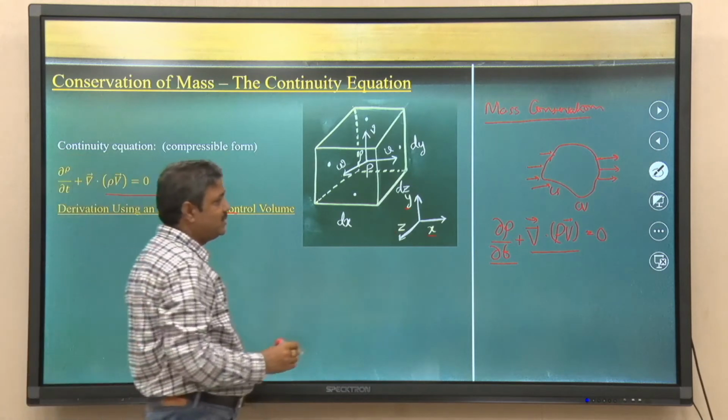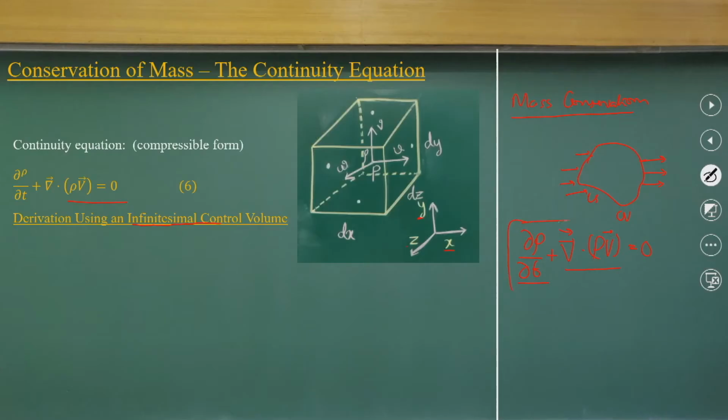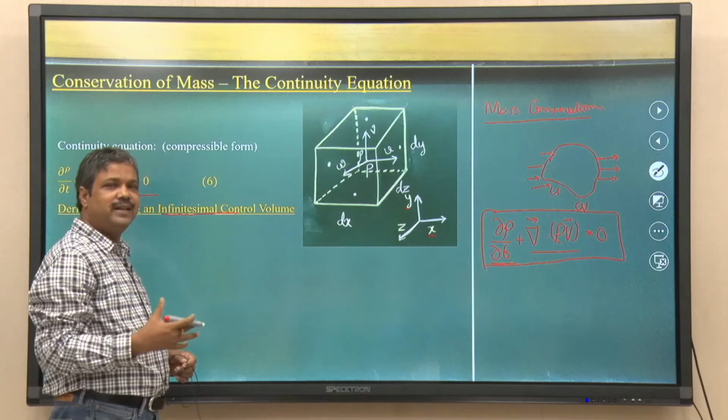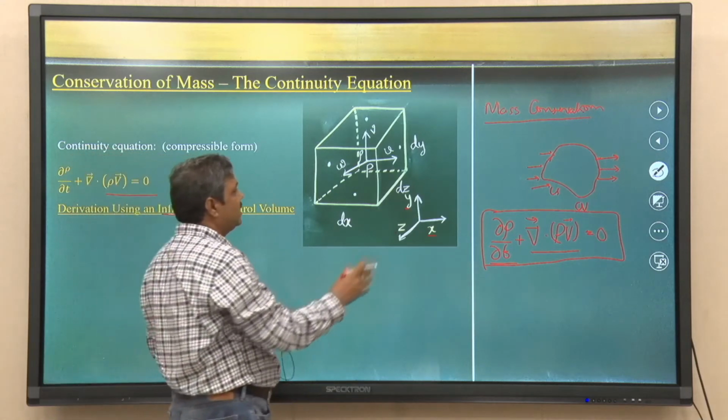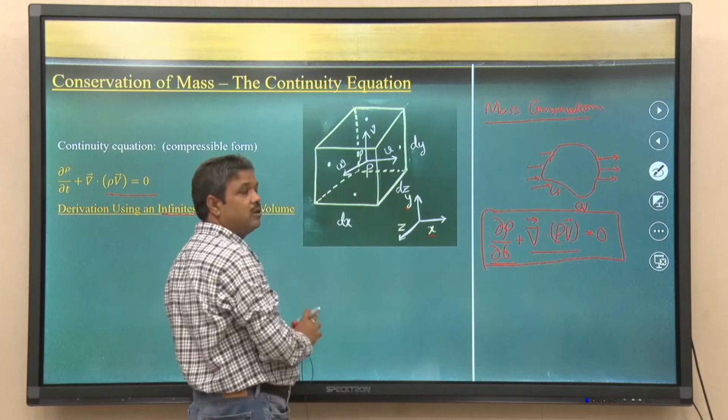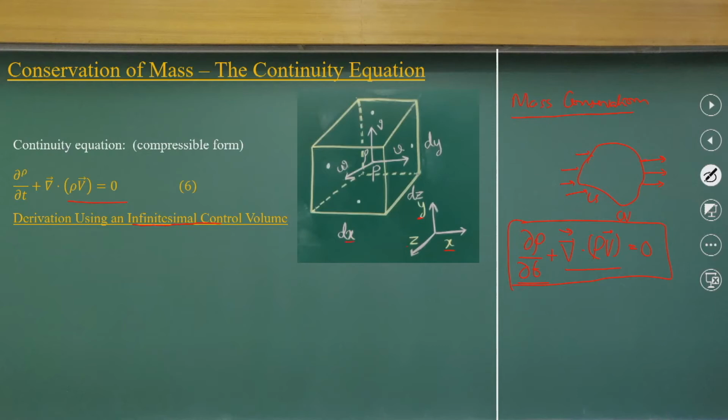As we are discussing, we are going to get the same form of equations we derived from the Gauss theorem, but here, to understand more clearly, we are taking a simplified control volume. We are considering a simplified parallelepiped control volume with dimensions dx, dy and dz. The velocity field is u, v, w, and as you know, the velocity is a function of space and time.